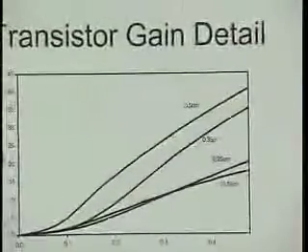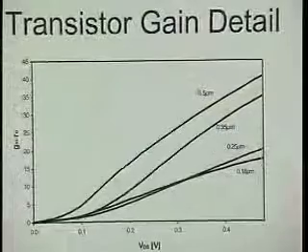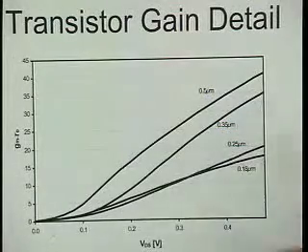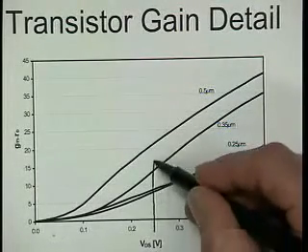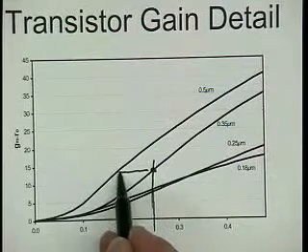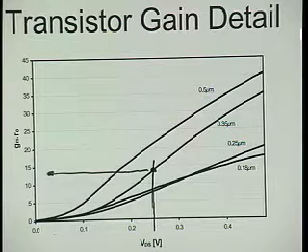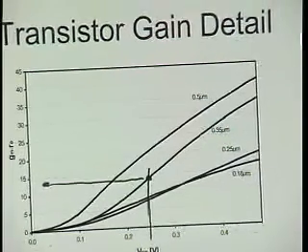So in our 0.35 micron technology, if we want to have a VDS min of about, let's say, 250 millivolts or so, then the gain we can get out of that transistor is 12, 14, somewhere around there. Right? And then again, as you pointed out, we're also going to have a load that also has finite ro. And so we may be getting half that. So if we want to get a bit of gain, we need a lot of stages. Plus, of course, if we really want gain, we probably are going to use just a tad longer than the minimum channel length.